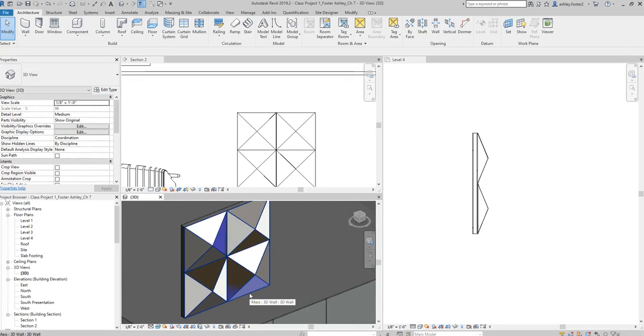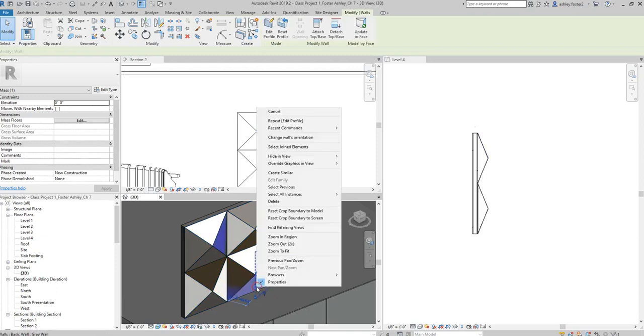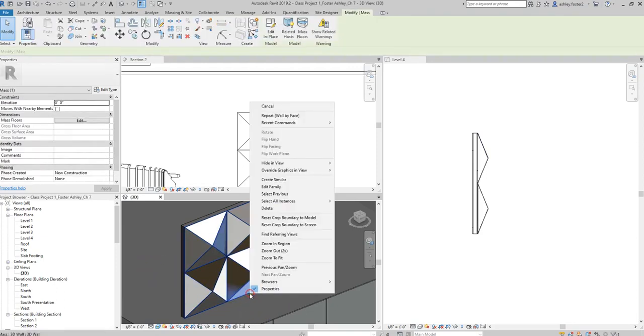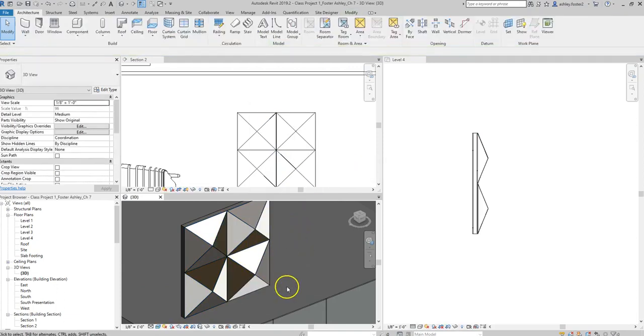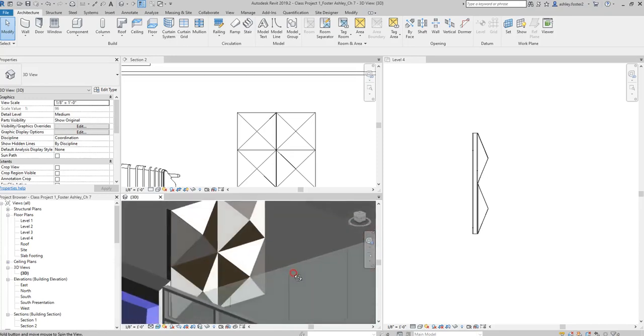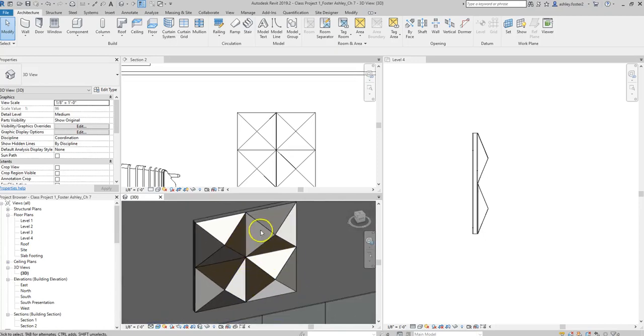And if you want, like say maybe you're not quite sure if all of those triangles were placed a wall there, you can select the massing. You can right click and you can hide that element, and then that way you don't see that purple coming through anymore, and so it looks like everything was placed really well. And that is your 3D wall.